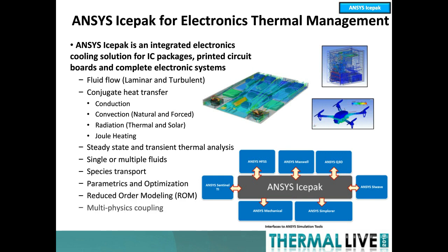One important capability of IcePack is its ability to perform multi-physics couplings with other physics solvers from ANSYS. So in this diagram on the bottom right, you see IcePack sitting at the center of some coupled physics analyses. IcePack can link with ANSYS HFSS, Maxwell, and Q3D, as well as SI Wave for electromagnetic thermal simulations. IcePack can also link with Mechanical for thermal structural simulations.